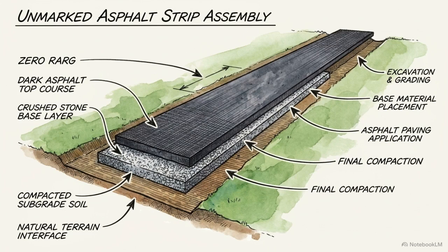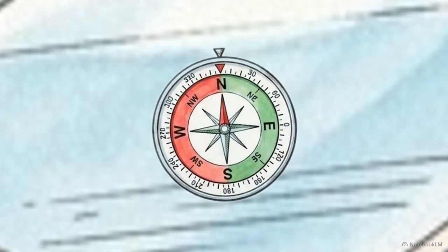We begin with a blank strip of asphalt. To integrate this into the global network, it requires a standardized identifier. Runways are named strictly by their magnetic direction, rounded off to the nearest 10 degrees. A runway facing 274 degrees magnetic becomes runway 27.